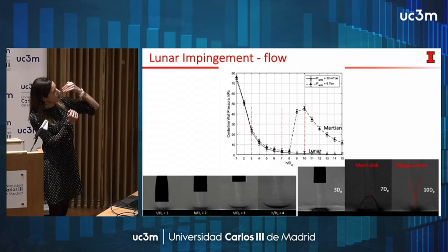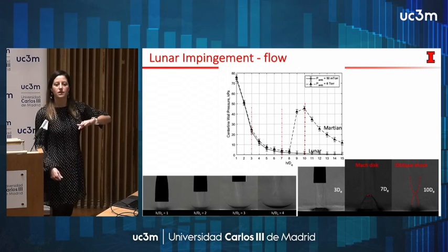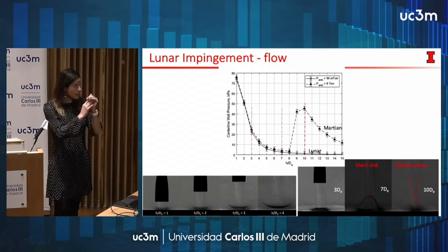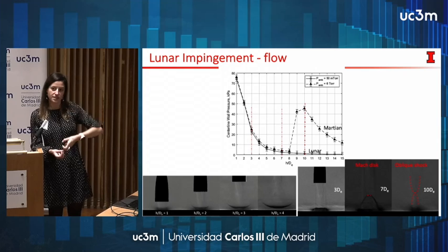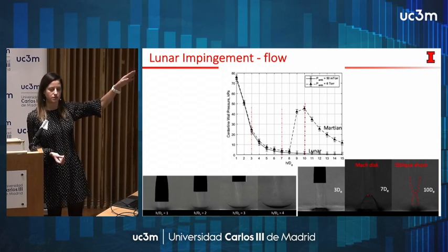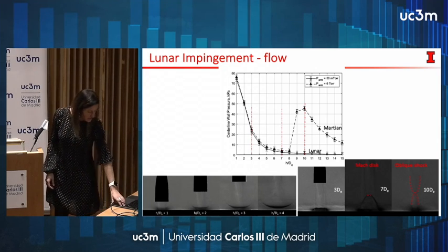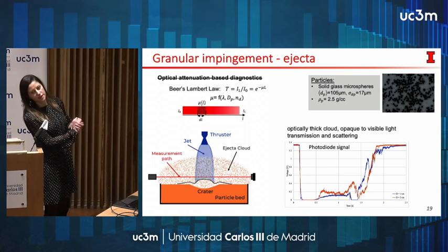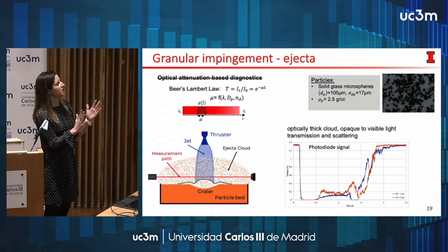And if you go farther away than 8 diameters, you transition to an oblique shock type of flow structure in which you are increasing the dynamic pressure in the axial direction and overloading the surface. So that's why the dynamics are so different for both cases. So very quickly, to something that I find very cool.